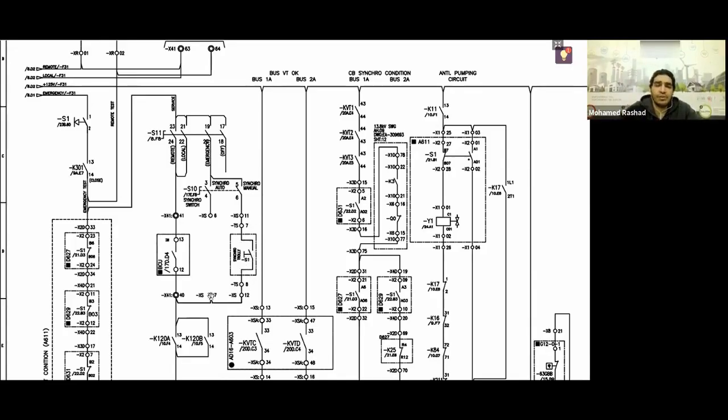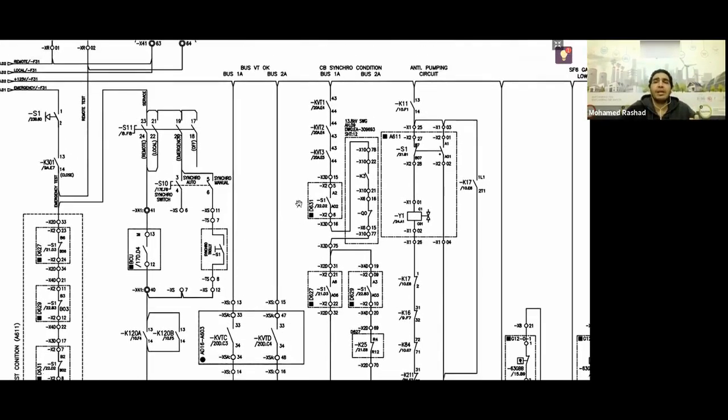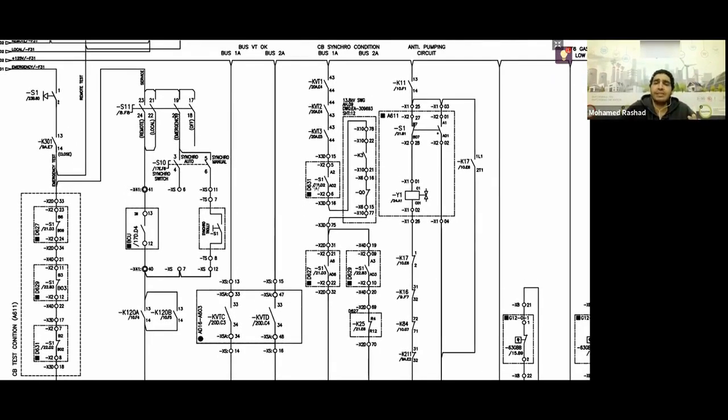All of this, it will come to you here, but for it to come here, the service position conditions must be met. What are the service position conditions? The service position conditions are that the main disconnector, the one below, is completely closed, and one of the buses is closed, or they are both closed. Additionally, since I am a transformer, the downstream circuit breaker is racked in. So these are the interlocking conditions.